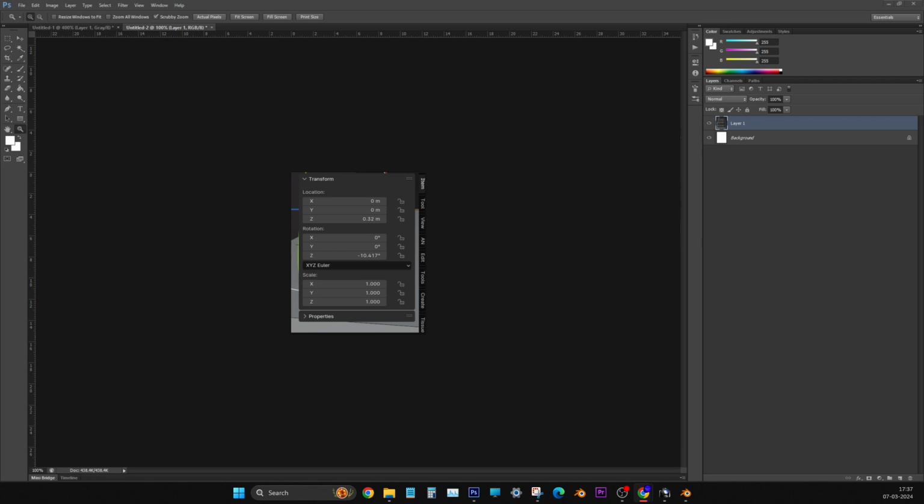I will tell you how we will do that. But only on the top, the steps should be there. On the bottom, it should be flat. Now we have to do the UV unwrapping. You have selected the faces. Go to the UV editing module, or just press back to previous. Yeah, now the viewport was maximized.